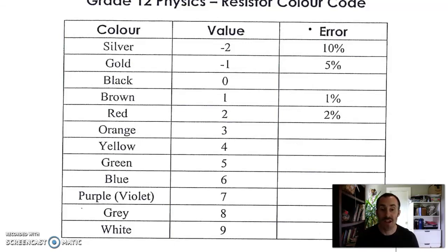When you're manufacturing resistors, you can manufacture them to different tolerances. You may have a resistor with a 10% tolerance, or a 5% tolerance. Those are the most common ones. You can get smaller tolerances as well, they're just more expensive and more precise for certain purposes.